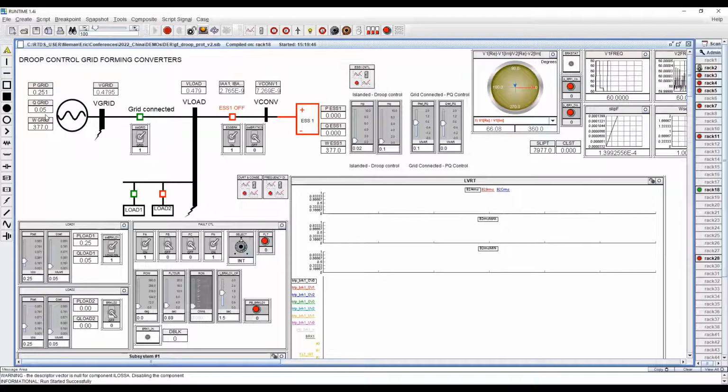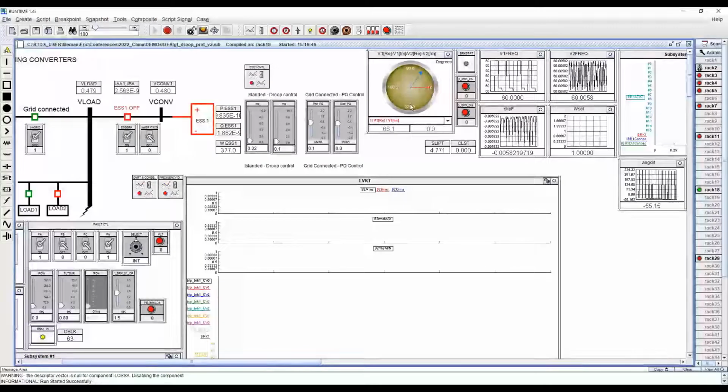The grid will provide power to the load initially. After the startup delay of 5 seconds, the DR bus voltage reaches the rated value. The DR breaker BRK1 here is still in open state. A vector display compares the phasors of the PCC and the POC bus. The frequency at each of the bus, the slip frequency, the reference frequency in per unit, and the slip time to 0 degrees are all monitored here.